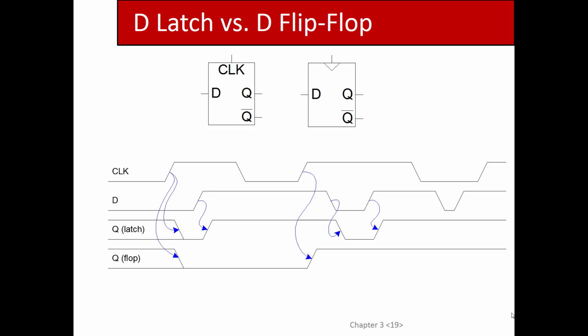So every time you have a rising edge of the clock, you expect there to be action on Q, right? You're going to sample D and bring it into Q. So D is 0, but who cares, it's 0 until there's a rising edge of the clock, which happens here. At that point, Q, let's see. Oh, this is actually comparing the output of a latch versus the flip-flop. So let's take a look at the flip-flop first.